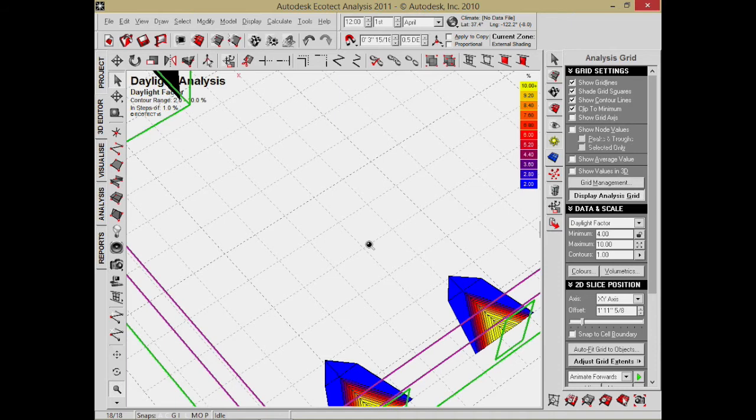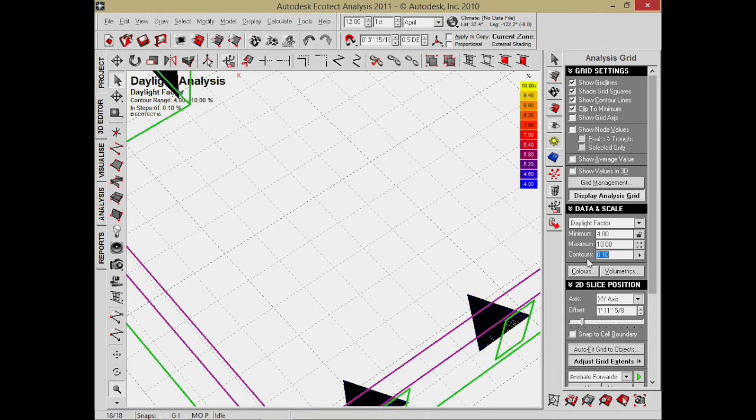It's almost like contour lines on a topo map. So if I put 2 in here, I should get something that's much grosser. If I put 6 in here, that should be very gross, only when it crosses a big boundary. If I put 0.1 in there, that's almost a little too fine. Okay, just get a little bit more contour in there.